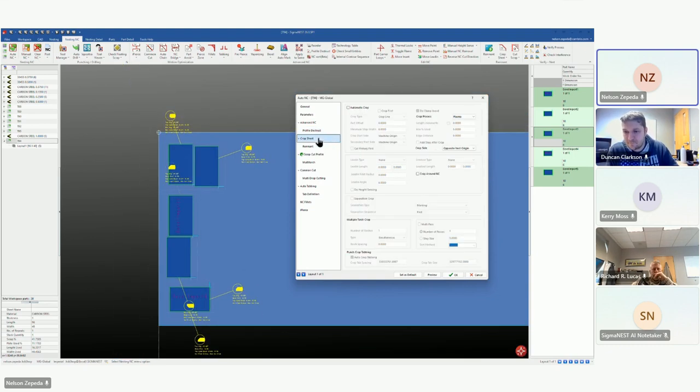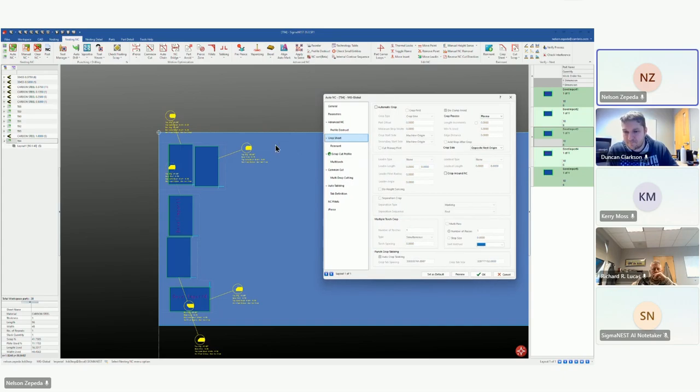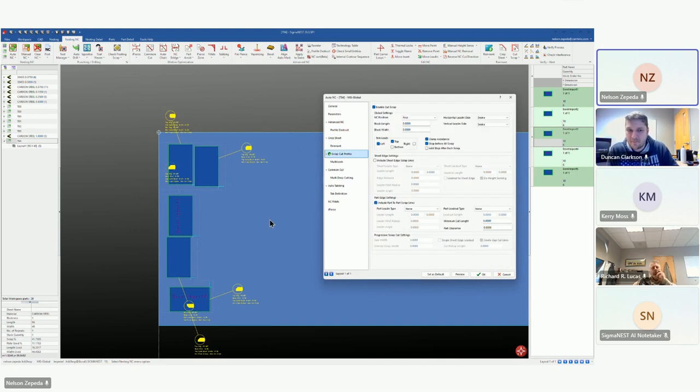And then our crop cuts, these are fairly self-explanatory, but the sheet cutoffs here, we can do straight line, we can hug the contour of your parts, so you can save that leftover material. We can do some scrap cutting, which is very similar to profile destruct, but this would apply to the skeleton of your material and come in and destruct that skeleton area.